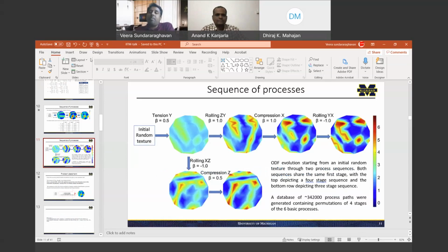Yeah, so you're right. Texture is a lower dimensional descriptor, which is basically volume fraction information. You're looking at volume fractions of different orientations in the microstructure. And that primarily affects certain properties, and you have higher order variation. I talked about Anand's work on 2-point correlations, which is much higher dimensional, which tells you the probability of a grain next to another grain, this orientation next to another orientation, for example. You also have grain boundaries. It's a very tough problem. You have microstructure with grain boundaries, you have slip transmission, etc.